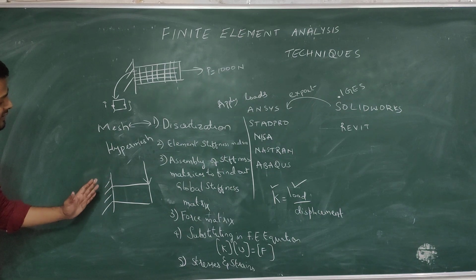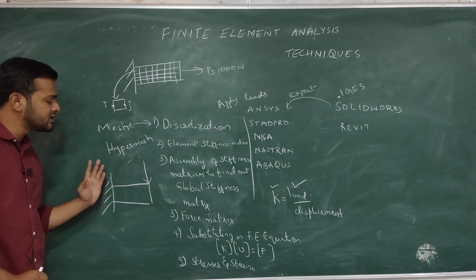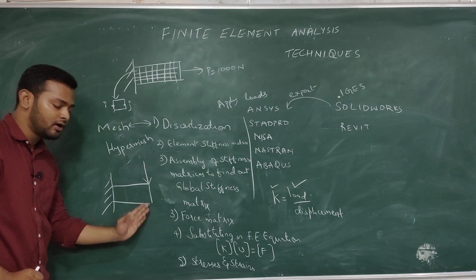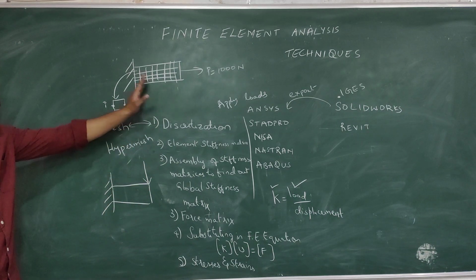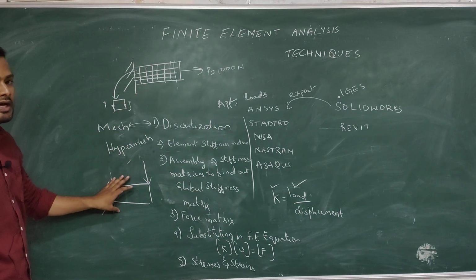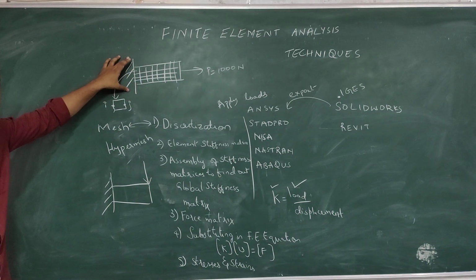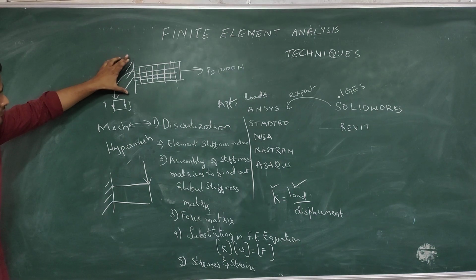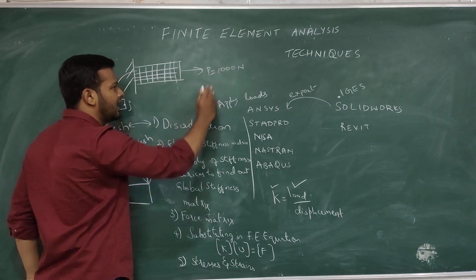So this is called a beam, because beams have 2 types of displacements. You will have to remember: one is movement in the lateral direction, the y direction, as well as bending. In this case, you only have movement, but there is no bending. So this is called a bar and this is called a beam. In the first unit, we will be solving the simplest problems, that is, problems on bar elements. These are called one-dimensional bar elements, because there is displacement only in one direction.